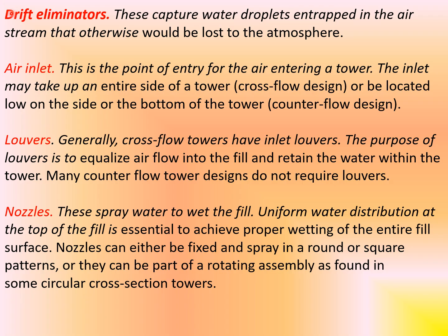Friends, at the end, let us see some portions or components of the cooling tower. First one, drift eliminators. These capture water droplets inherent in the air stream that otherwise would be lost to the atmosphere.